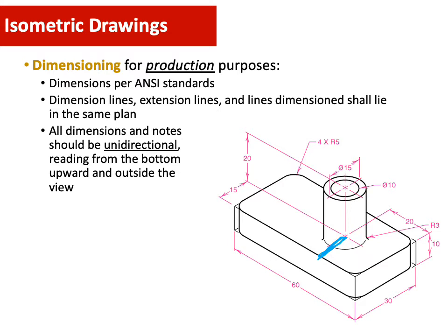You need to put it outside of the object, and it needs to be unidirectional, same as where you want to know the dimensions. So this is for the height of the holes until this point of center. Here is maybe around 15 inch. This is the diameter, and this symbol shows the diameter. This is going to be the length. So it needs to be unidirectional and outside of the views.